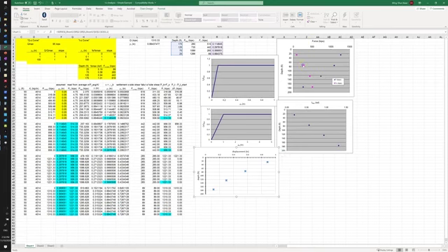And this is powerful because it also gives you the side frictions and also the loading inside the piles. So which are those numbers there. This gives you the average loadings on the piles at different elements, at different segments, and also the side frictions of the piles.